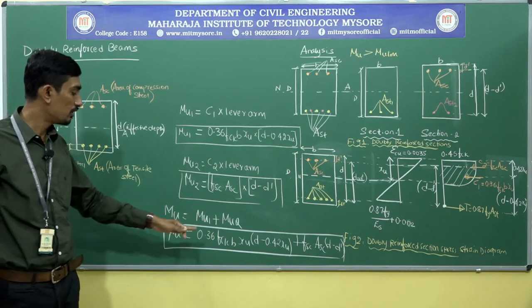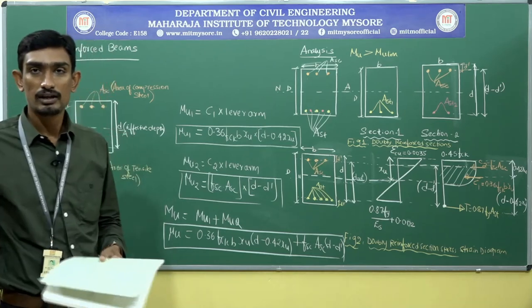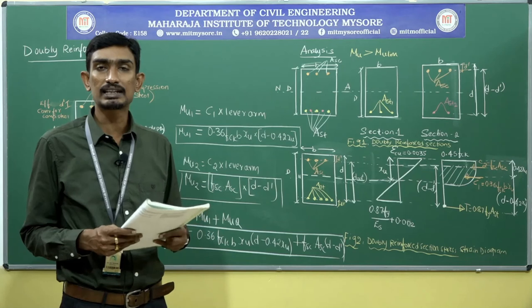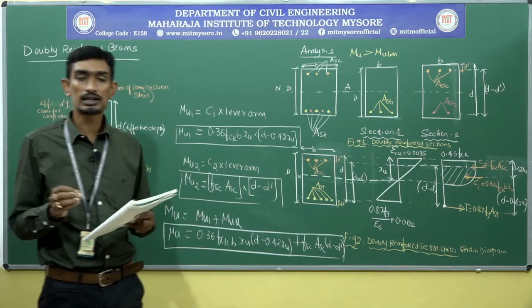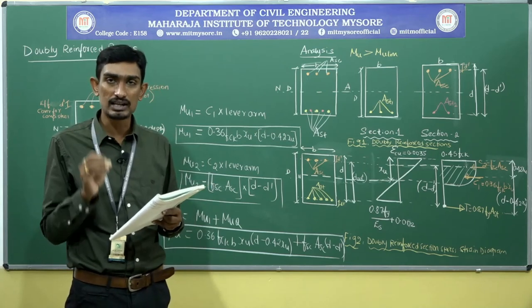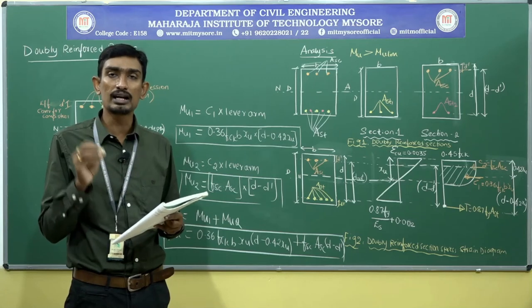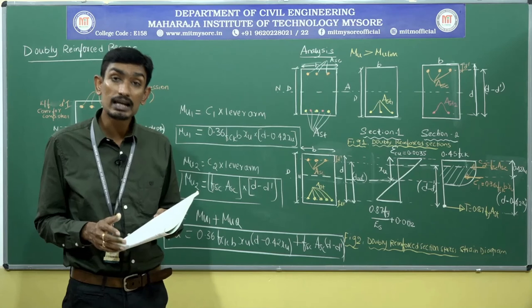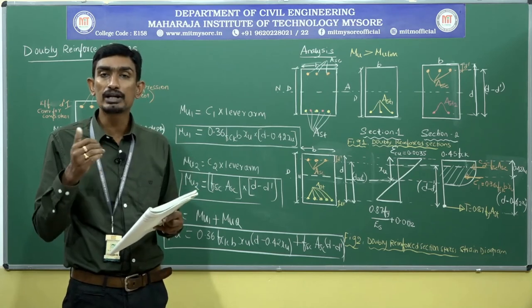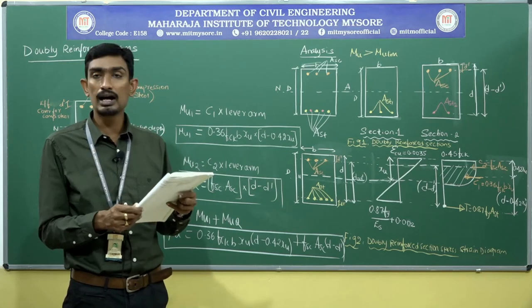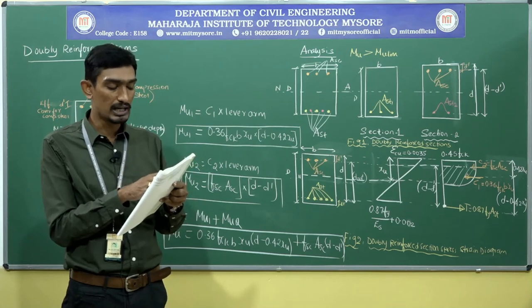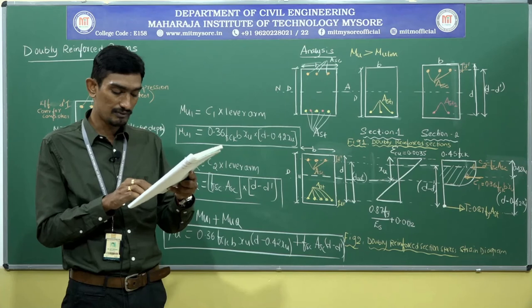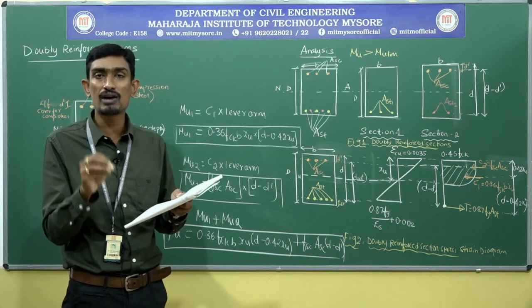Coming to the IS 456, for the singly reinforced section we have been defined in Annex G, page number 96. We have discussed clause G 1.1. Clause G 1 is for rectangular sections. Till now we have analyzed only rectangular beams, or rectangular cross-section beams. G 1.1, which we derived till the last session, is for singly reinforced sections. Now we will come across G 1.2, that is for doubly reinforced sections. In IS 456 they have clearly defined G 1.1 as section without compression reinforcement, that means a singly reinforced section, and G 1.2 as section with compression reinforcement, clearly indicating it is for doubly reinforced.